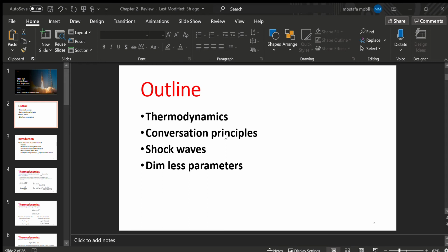So where do we want to go with all of these formulas listed here? We essentially want to go to the definition of gamma and the relationship we have for gamma. We define gamma as the ratio between the constant-pressure specific heat capacity and the constant-volume specific heat capacity. Based on the equation you see here, we can see that Cp equals Cv plus R, and Cp over R is equal to Cv over R plus 1. That's very simple, right?